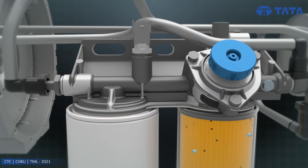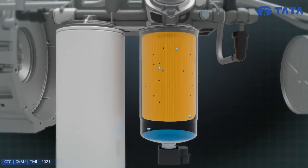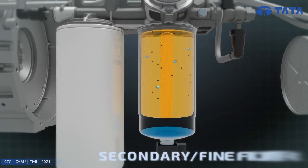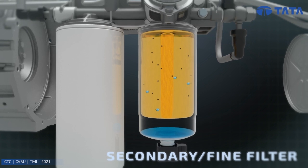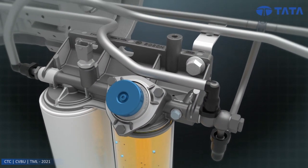In the second stage of the fuel filtration process, the fuel passes through the secondary or fine filter, which filters out the tiniest particles and separates water from fuel. The water gets collected at the bottom side of the filter.